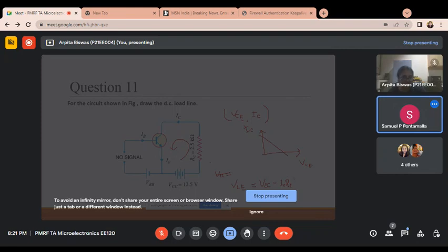So you have to find this point, okay, and this point. This means where the IC value is 0. From this equation, now this is equation number 1. Here you just have to put when IC value is 0, then what is the value of VCE? First calculate this, and then calculate when VCE is in that point. What is the value of VCE? 0.